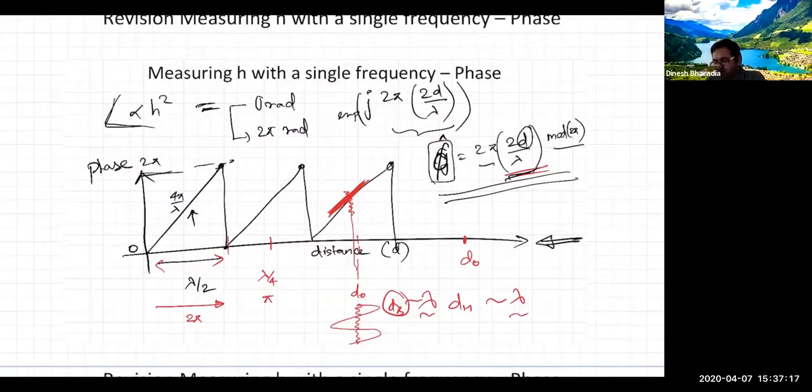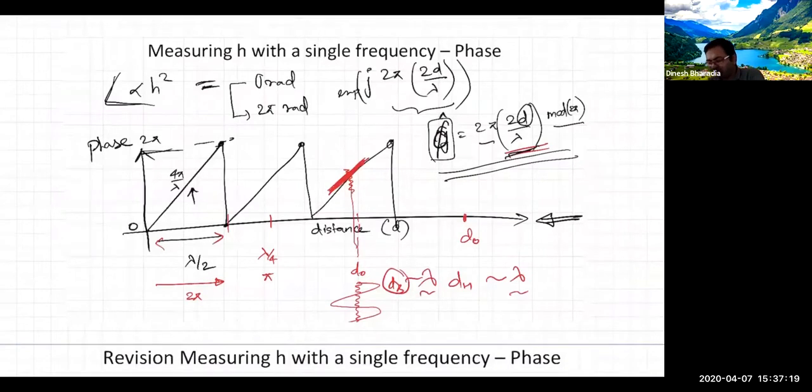So let's start with the very simplistic thought process. What is a simple thought process? My simple thought process is this: I want to make sure that the breathing and heart rate are confined to one cycle here. Everyone clear on why I want to confine that to one cycle? So that there is no aliasing effect.